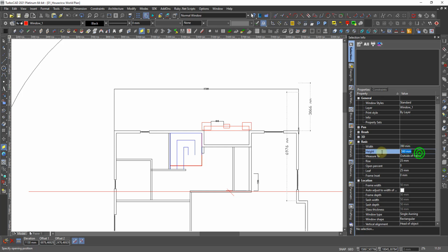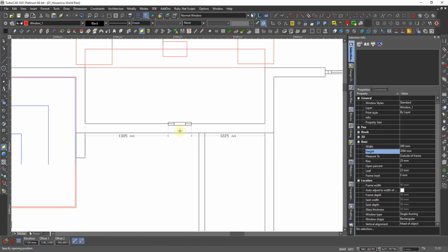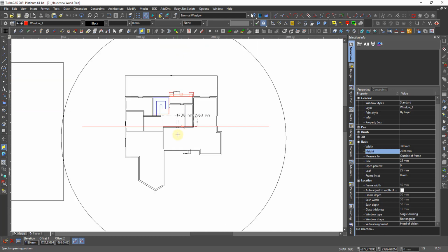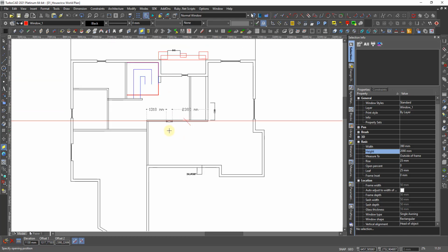And then it should be 2090 because they're the same height like the door. And I put it here, about here, something like that. Then we have space here. What I didn't do was to adjust the height, because when we changed the dimension, the height of the window, the insertion height, that was 2320, also changed.